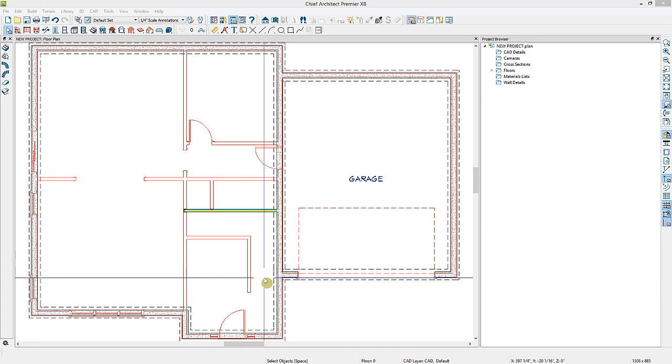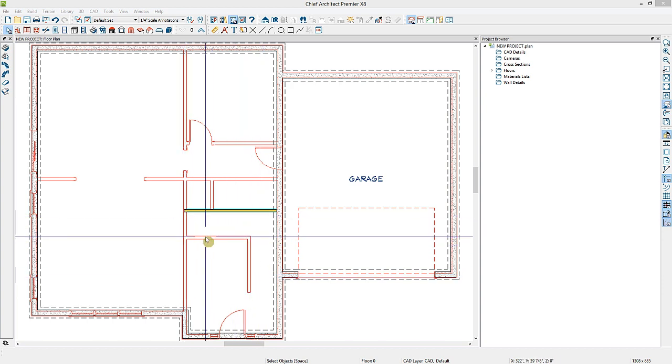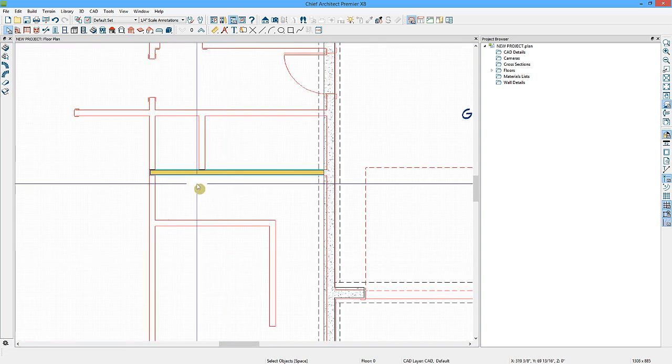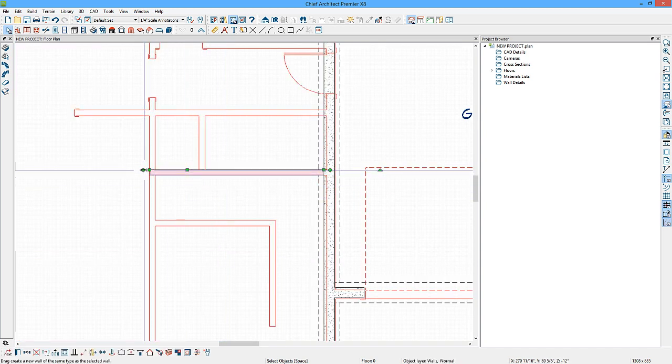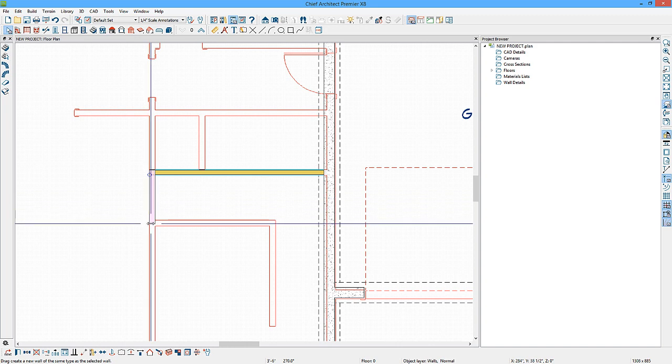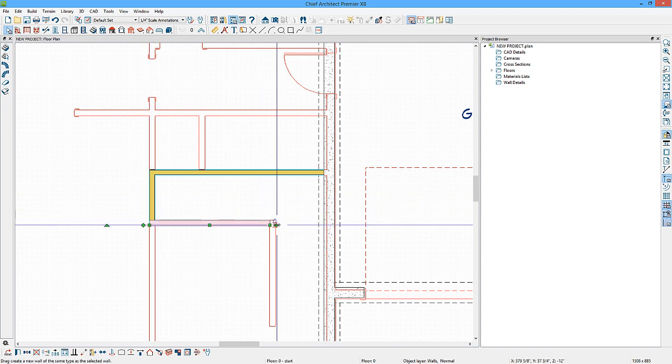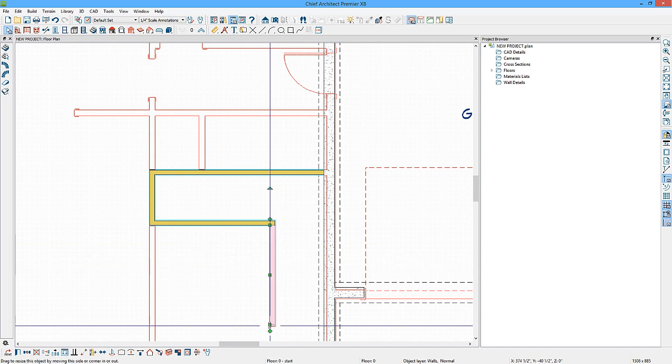Now I want my staircase to be enclosed in walls shaped just like the ones on the second floor. So here, with my reference display active, I'll select this wall, use the same wall type edit handle, drag a wall down this direction, drag another one in this direction, and another one in this direction.